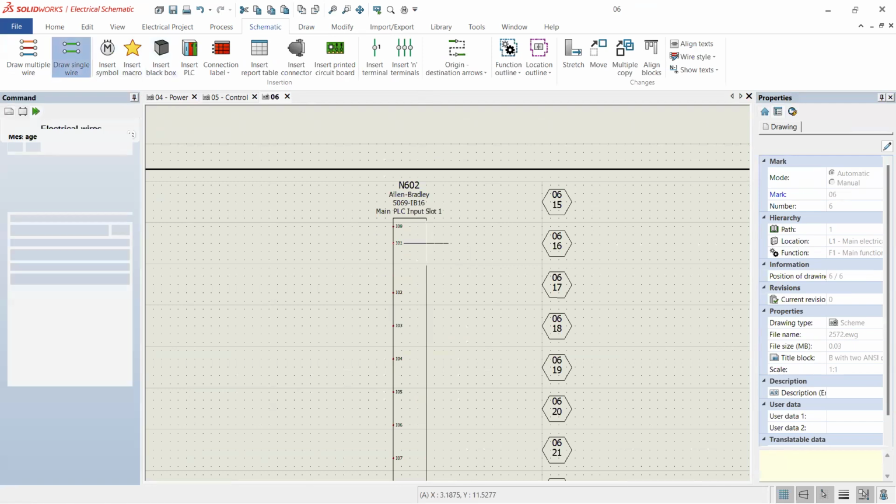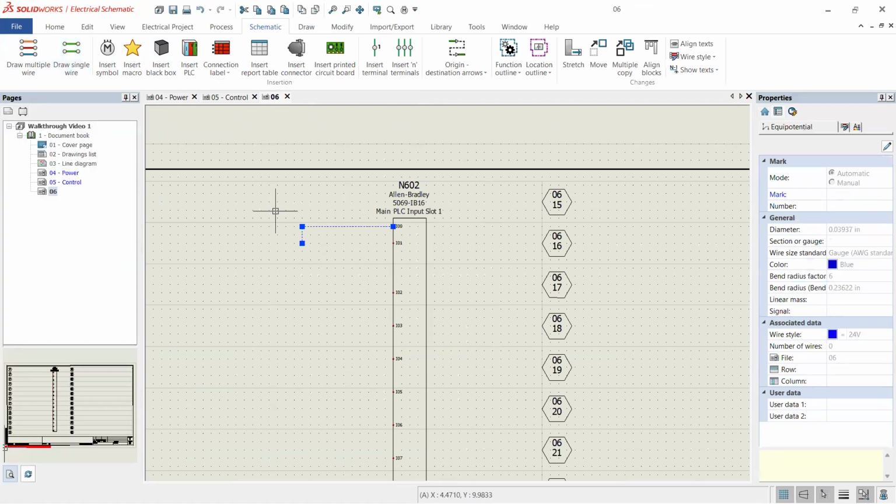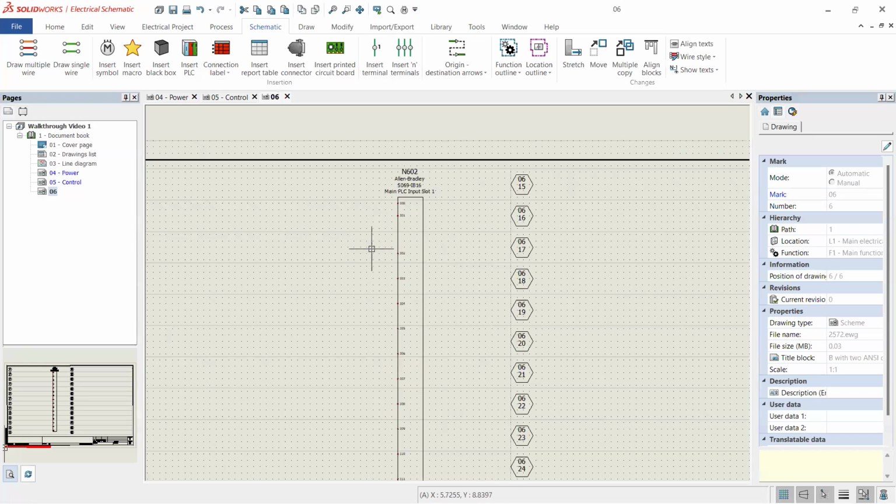So when I draw wires, things line up correctly, right, to the grid. So that's why when you're creating symbols, remember 2.5, multiples of 2.5. I have a suspicion that has to do with the 2.54 centimeters per inch thing, metric to standard conversion, I think. But I haven't been able to confirm that.